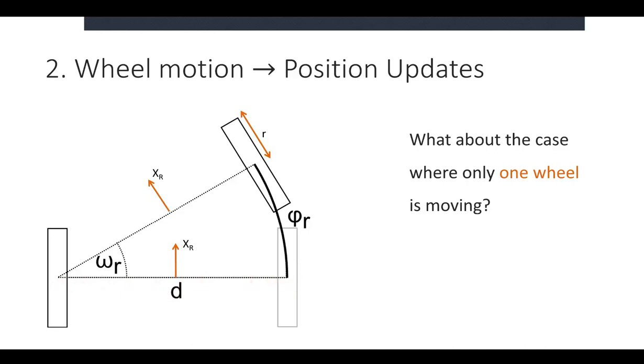And typically, we're going to pick a single point in the middle of the robot to denote the robot's position. So the XY coordinate, let's say, of our robot is going to be defined at that one middle spot, which we'll put right here between the wheels. The x-axis in the robot's perspective is always going to be pointing out the front of the robot.